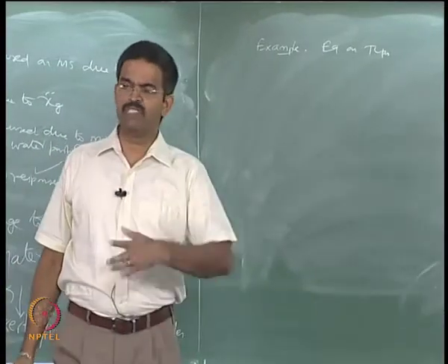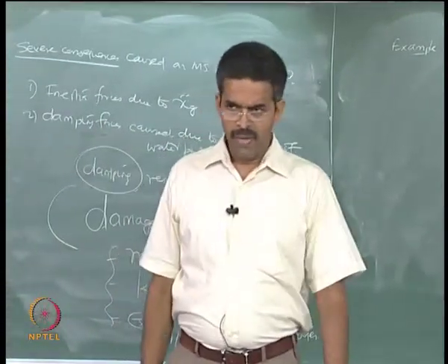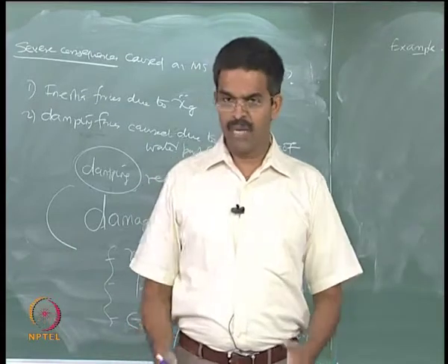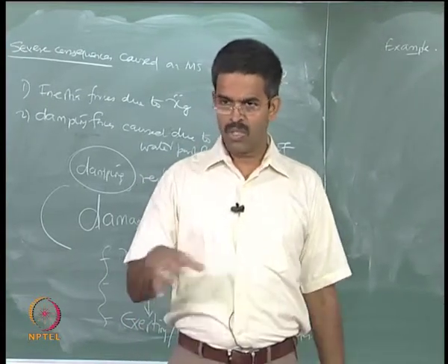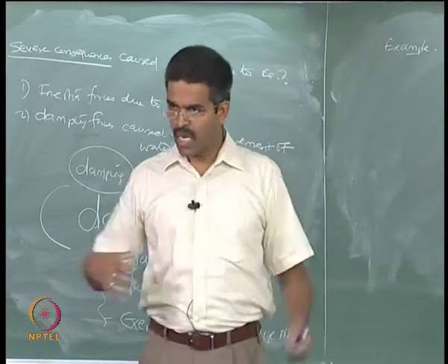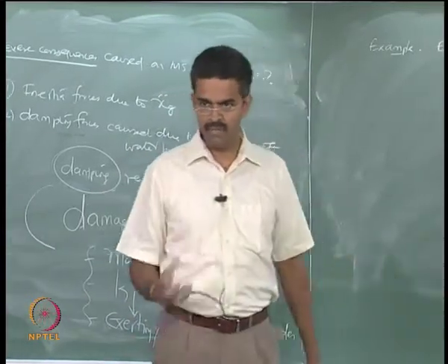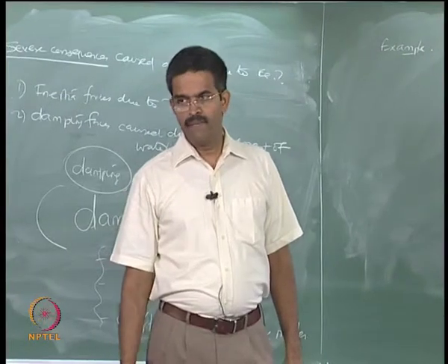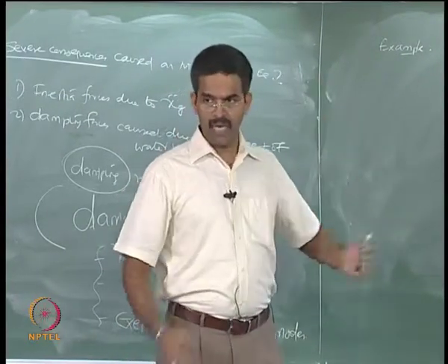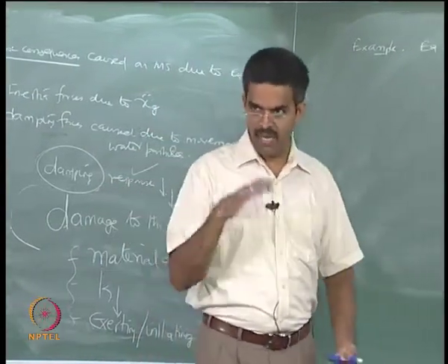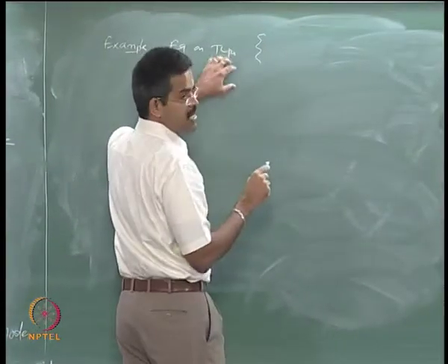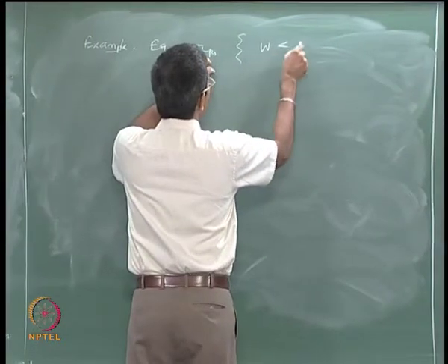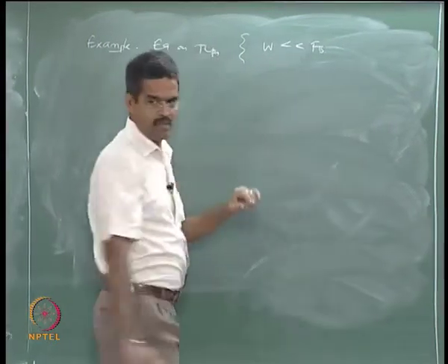A TLP is a flexible structure. It is large in size but it is not massive, because the members are pontoons and columns that are hollow. It is designed for excessive buoyancy, and the weight is very low. I think we all agree that a TLP has a very special design phenomenon where the weight is much lower than the buoyancy, is it not?